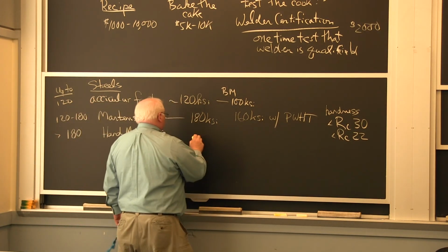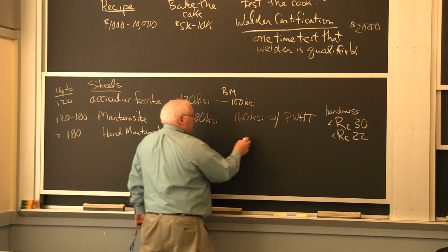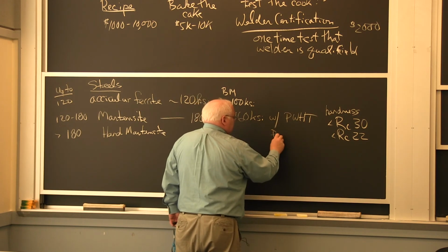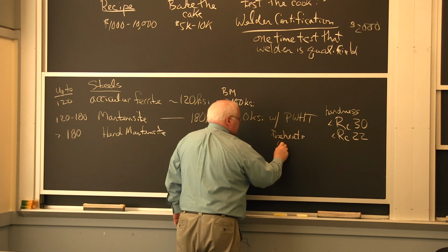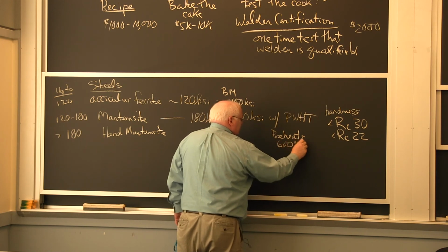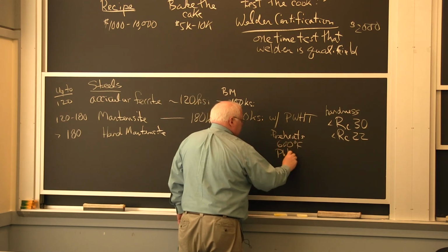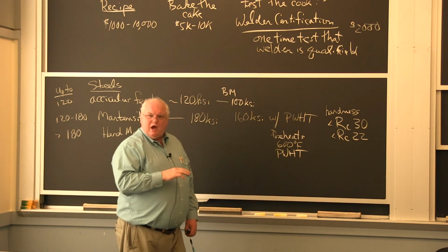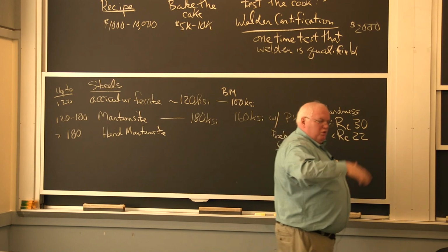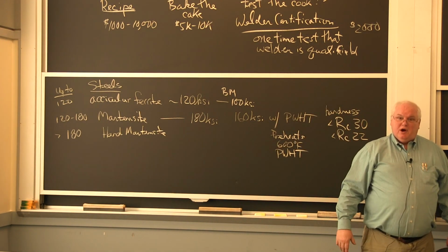I mean, yeah, you can have higher strength base materials, but preheats of 600 degrees Fahrenheit and post-weld heat treatment required. It's very expensive. This is the problem when they came to me and said, oh, we want to use 4340 in our America's Cup yachts.